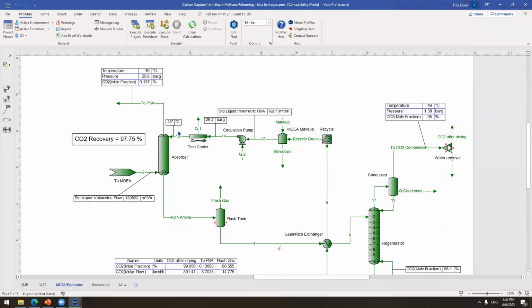If you're not going to cool it enough, then it wouldn't work, because it would still be hot and would not be able to absorb the CO2. It's an absorption column, and as I said before, the heat of the reaction, the heat of the absorption, would basically lead to the CO2 coming out of your absorber, and it would not absorb inside the amine.